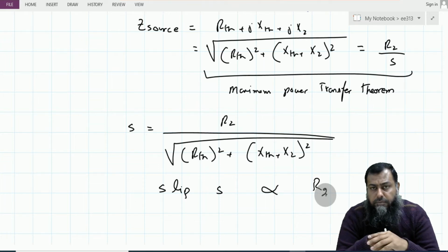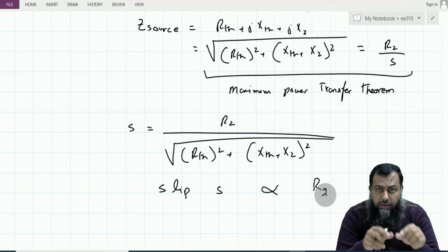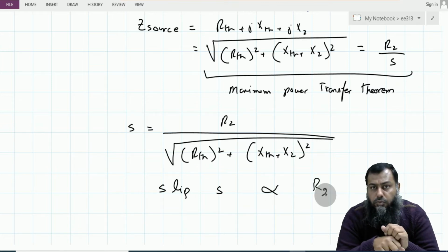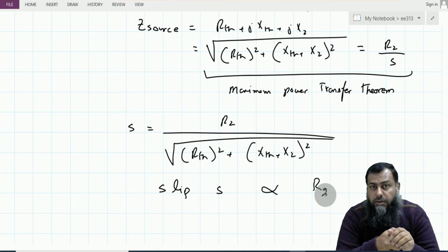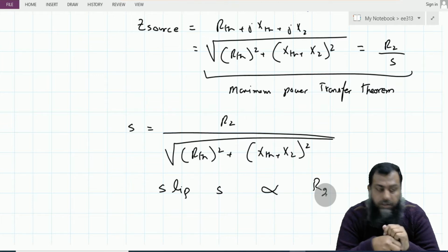Whereas in a wound rotor induction machine, we have arrangements such that the value of the rotor resistance R2 can be altered and varied through external connections. And therefore, by using the external connections, we have a provision that the slip can be varied for that particular machine. And this is a clear advantage of the wound rotor induction motor over the squirrel cage induction motors.